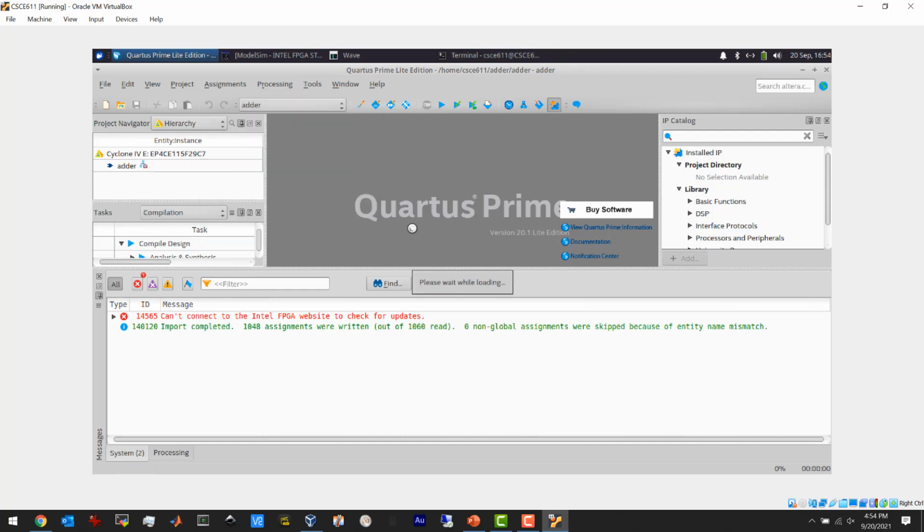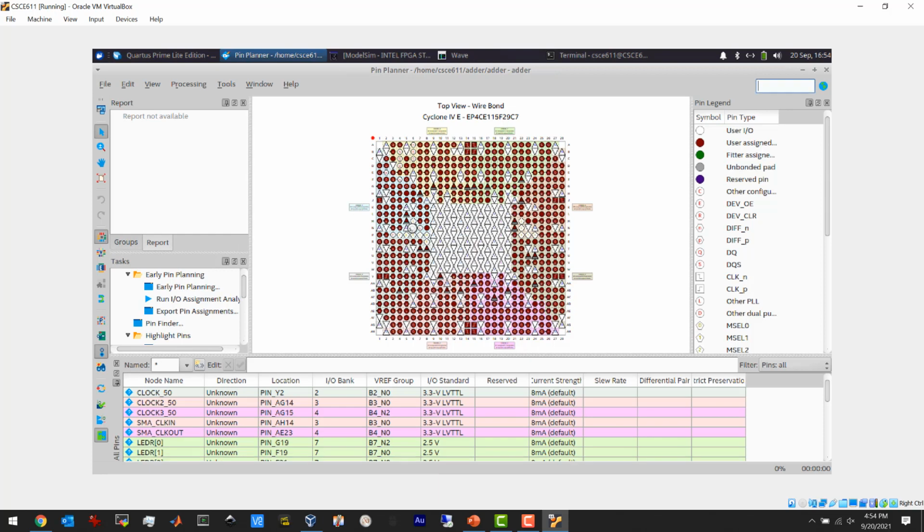And it actually shows you, this is the bottom of the FPGA, these are all the pins, and if you look down here, you can see for every one of those pins, there's a symbolic name. All you have to do to connect to a pin is put one of these names in the module line for the top level design, the top level inputs and outputs,